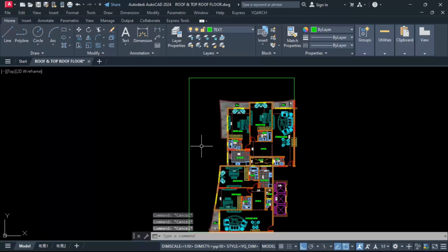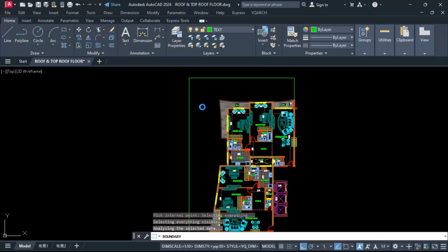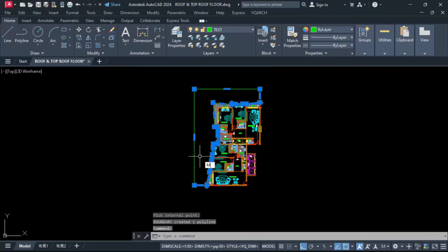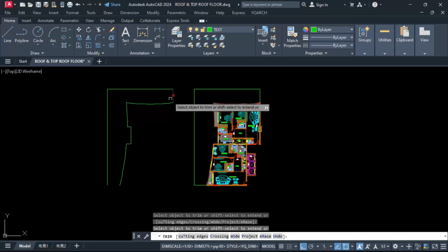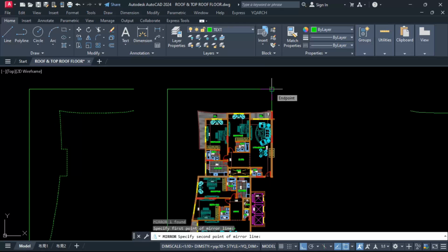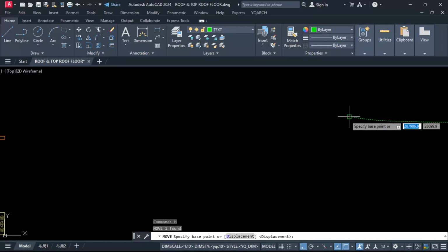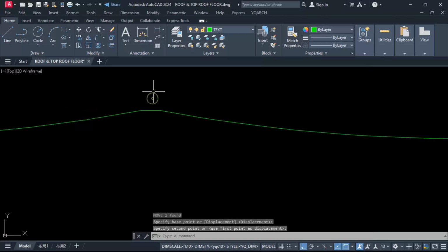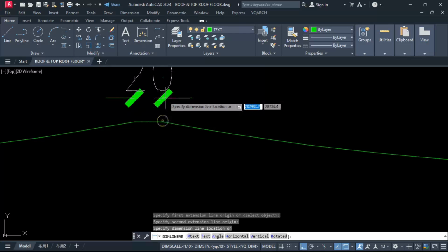Okay, let this boundary command. Okay, polyline, click OK, click inside. So we are getting inside outer boundary. Okay, same, let this copy here and trim rest of the part same as it is, just mirror this portion. Take any reference point, this is okay. Erase source object, no. So let this join, and same will apply one more mirror other side. Okay, straight to downward. Okay, we will match 20 centimeter exactly we are getting.